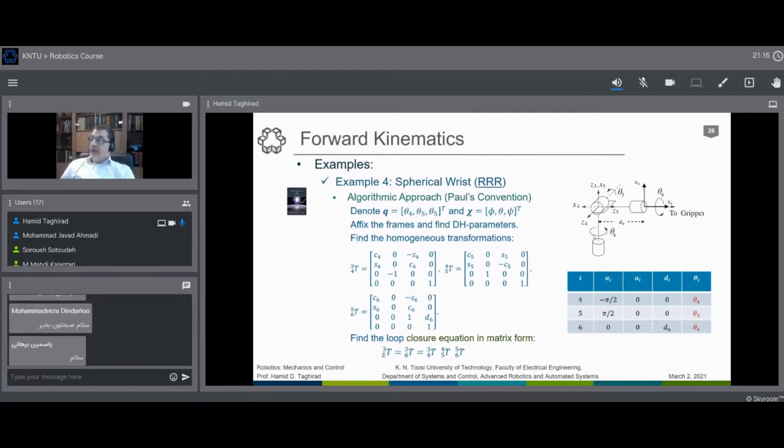We have an angle theta 4 about this Z-axis, a perpendicular joint. We have an angle of rotation, as you see, in this direction, which, if we call it X, Y, Z, is in the base frame Y direction, but we call it Z4. And then we have another actuator, again perpendicular to them, in this direction, which is again, as we see, in the Z5 direction.